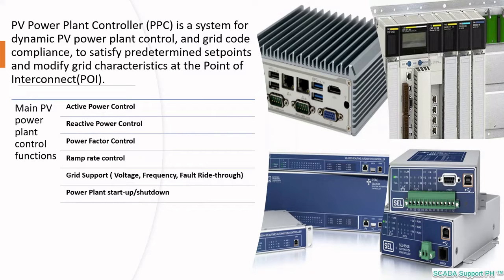Although each system has different requirements, most PPCs should be able to control the following parameters: active power, reactive power, power factor, ramp rate, as well as those grid support control requirements like voltage, grid frequency support, and fault ride-through.